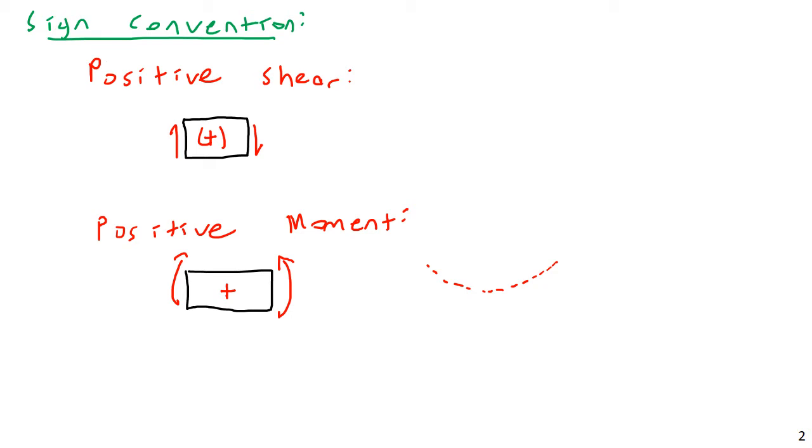We use that sign convention for a couple of reasons. One, it works nicely with mathematics. Concave up is positive bending, that works very nicely. Also, from the point of view of civil engineering, which do you think you encounter more often, positive or negative bending? Generally positive, yes, because the main reason we use beams is to resist gravity. We use them to gather loads up to resist gravity: weight, live loads, self-weight, dead loads, that sort of thing. Although we haven't learned how to work with load combinations yet, we will.